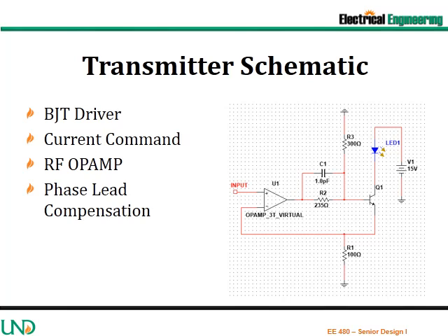The high-speed op-amp unfortunately does not have the required voltage range to drive the laser diode directly and sense the current as well. This forced a requirement to utilize a transistor to drive the laser diode. A BJT was chosen specifically because it is a current-controlled current device. MOSFETs have additional capacitance which reduces the speed and raises ringing.